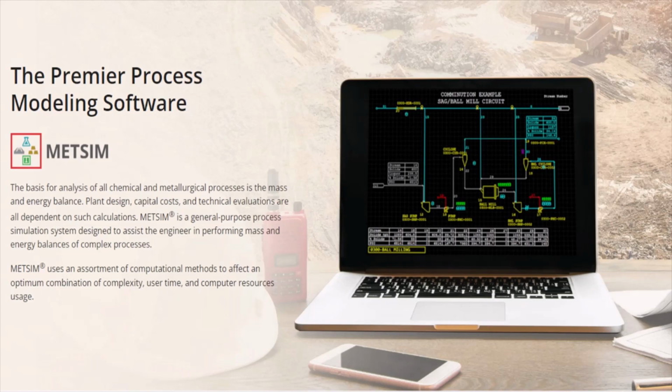So you can give METSIM the option to input all the other data and then put your ball mill in the forefront of it. So you input your actual flow rates, your inputs, your outputs, your electrical supply, and everything, and it actually sizes a recommended size of the ball mill. This is one of the advantages of actually using METSIM in the hydrometallurgical sector.